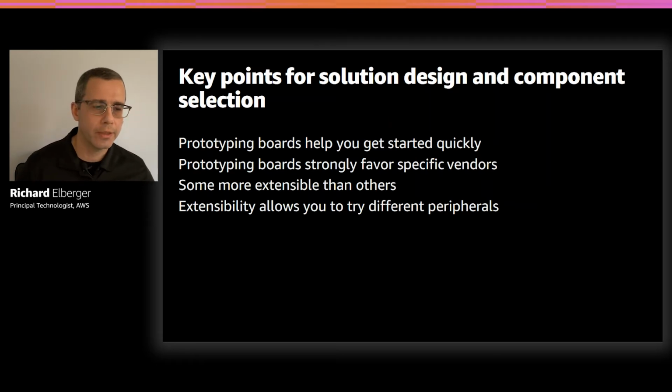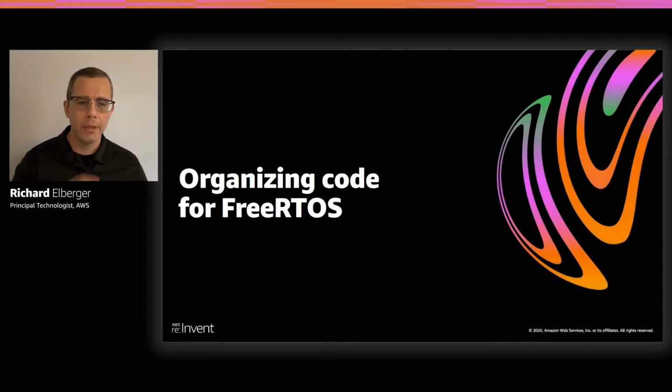So now we're going to get into the core of this talk. Now what we have are peripherals in the MCU. What's next? Well, FreeRTOS supports virtually every microcontroller family out there today. It supports ARM Cortex-M and Cortex-R, which is really the bulk of microcontrollers on the market today. It supports ARM Cortex-A, even though that's not a classic microcontroller; it's an application microprocessor. But also, FreeRTOS supports Espressif, PIC, and RISC-V. All these architectures can take advantage of FreeRTOS, and FreeRTOS can take advantage of these microprocessors. So let's get rocking on exactly what we're going to do with this.